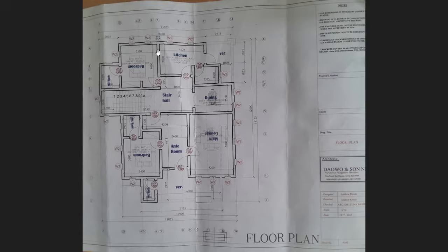We have the width of this particular bedroom to be 3.725, because I'm factoring in the thickness of the wall. You can see that the dimension here is only 3.5 meters, but that is just inside face to inside face. So you need to actually consider the width of the wall when you're creating a structural model. So we're going to take this dimension to be 3.725.